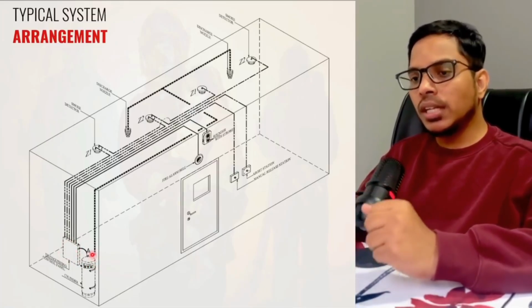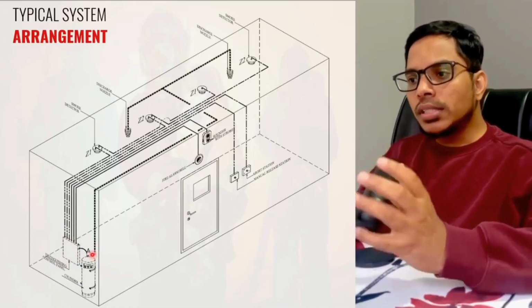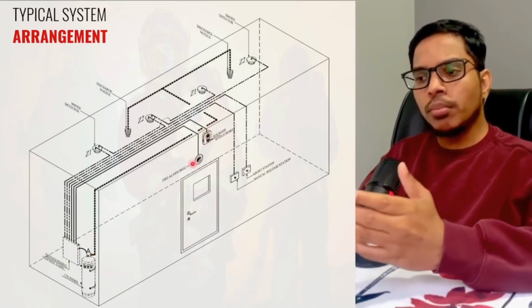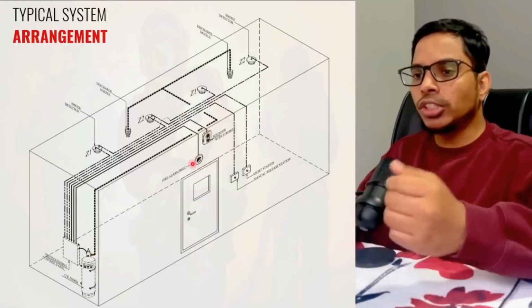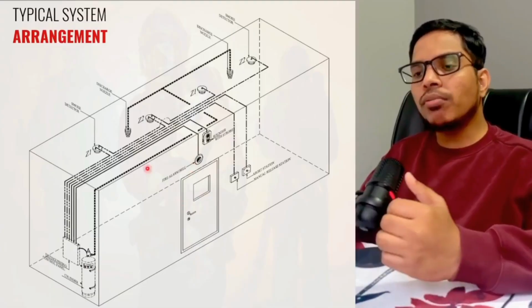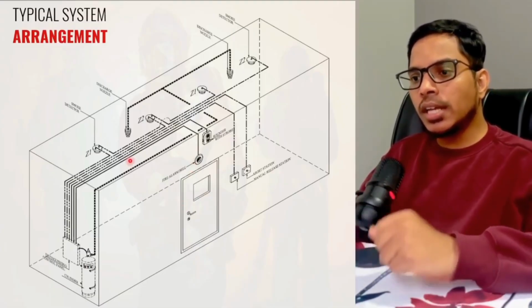from the cylinders. And the second most important point, the system first triggers the horns, horn strobes or bells, or notification devices in short, to warn the people so that they can evacuate from that particular room within this 30-second delay period.